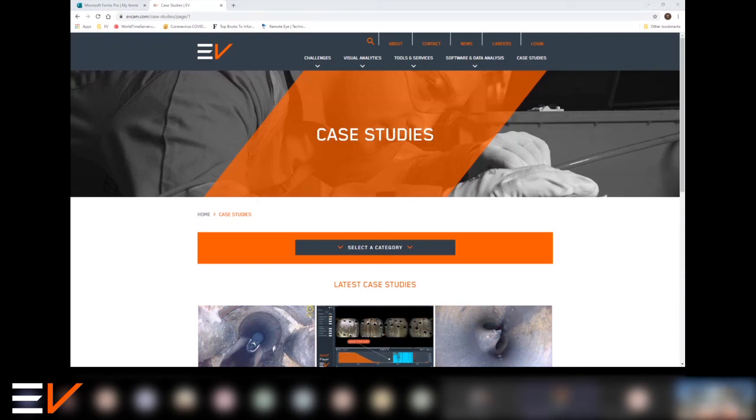Yeah, we've got one here asking, what is the highest deviation that you've ever deployed the camera at? Well, that's a good one. I'd have to check, but I remember seeing a number of clips with video tractors, video whilst tractoring, even some coil work where we've been going significantly uphill. So we've pretty much done it all. And with the flexibility we have on conveyance, it could be gravity deployed. We do a lot of pump down work in the US, of course, for the plug and perf frac market. But again, with that ability to physically see what's going on in real time whilst tractoring, this has been a terrifically successful service in and around the North Sea, Gulf of Mexico, places where there are deep, long horizontal wells.